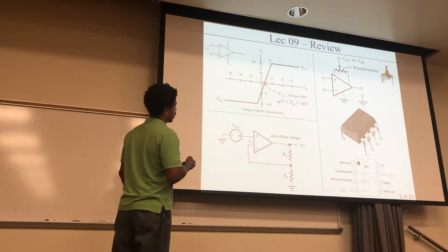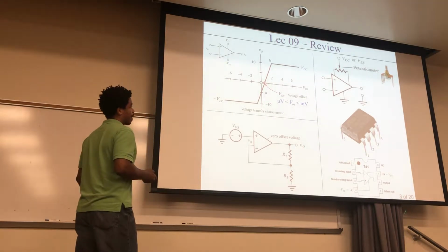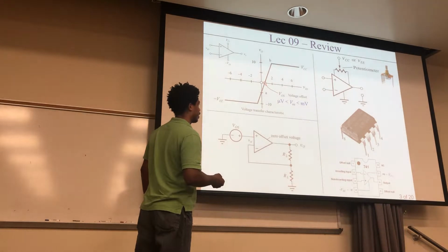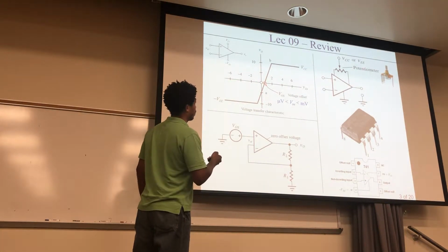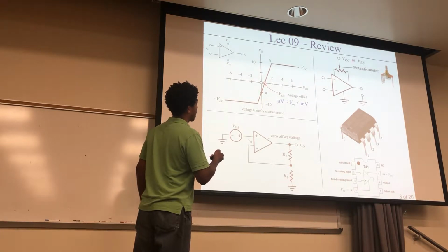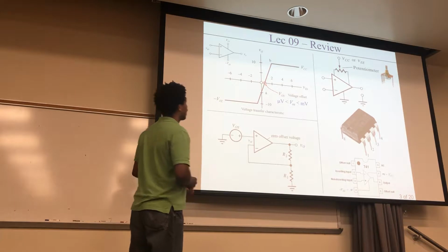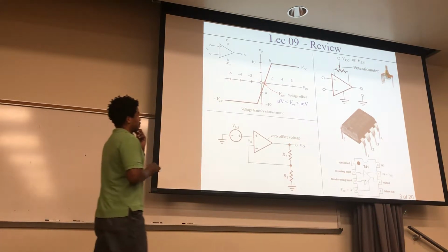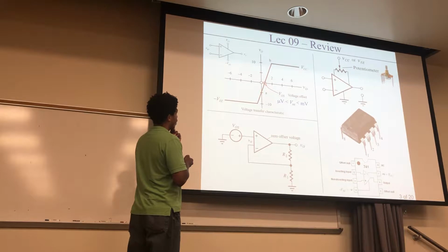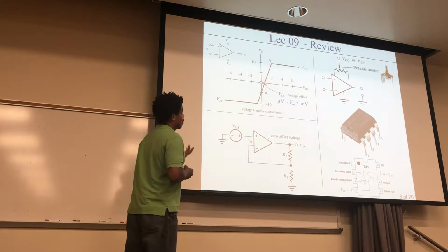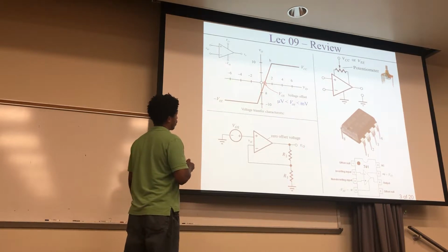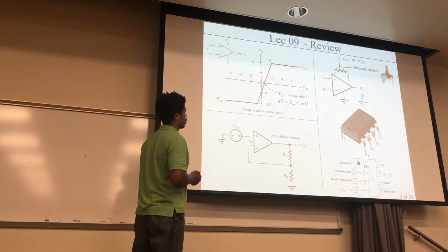If you really want to get rid of that, one thing you can do is attach a potentiometer. Here is a typical type of op amp, and if you look at the ports, you can attach a potentiometer to this and get that offset to zero. Now, I can imagine that sometimes you may want an even larger offset, or to change it depending on what type of signal you have coming in. Maybe you actually do want clipping, so you might want to change it for that reason too. But that's how you do that with the potentiometer.